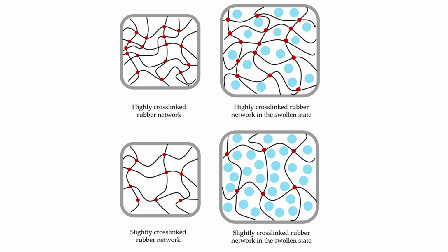Cross-link density in polymers refers to the concentration of covalent bonds, cross-links, connecting individual polymer chains, forming a three-dimensional network, which dictates material properties like strength, rigidity, and solvent resistance. It's measured indirectly through methods like swelling tests, ASTM D2765, dynamic mechanical analysis, DMA, or rheology, where higher density leads to increased hardness, better thermal stability, and reduced swelling, while lower density results in more flexibility.